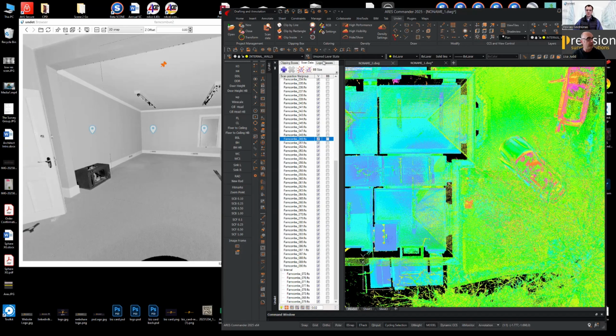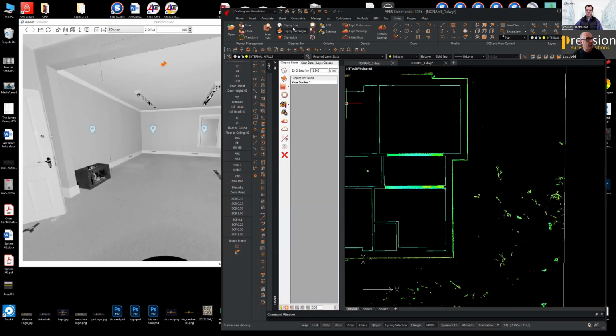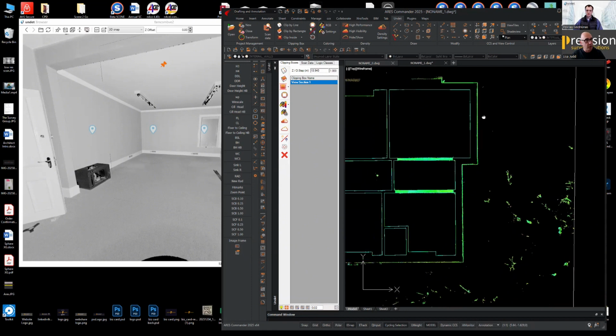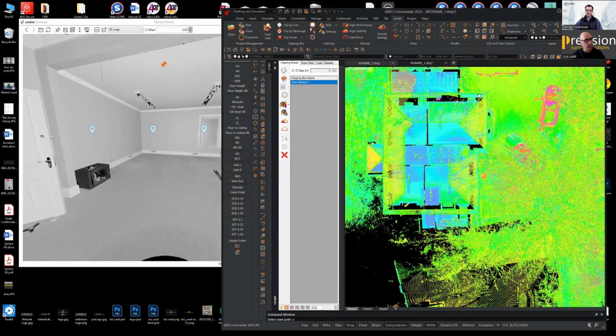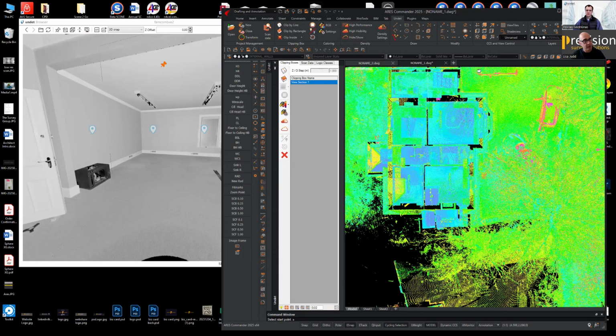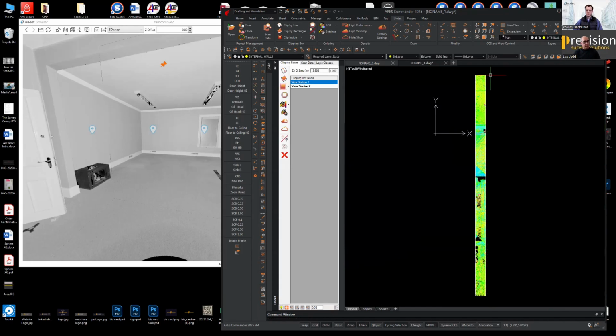And I can do one of two things. I can either use the clipping box that we had. So let's go back to that, and I'm going to clip by a line this time. We want to go down somewhere near the front of the building. So let's double click that, and I'm going to make that our clip. What it will do is clip us, in effect, a vertical section.